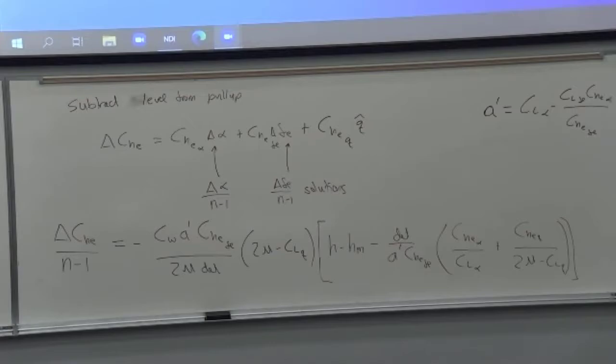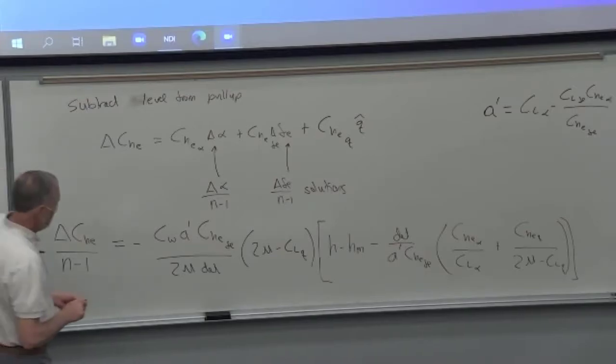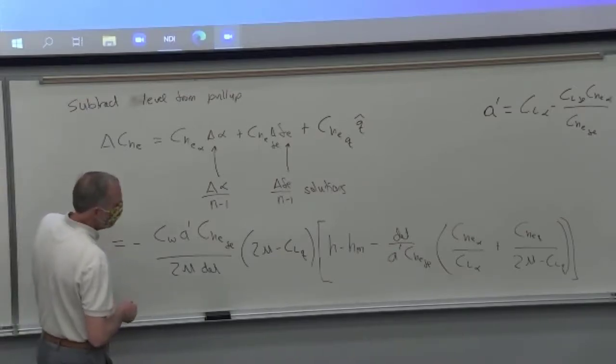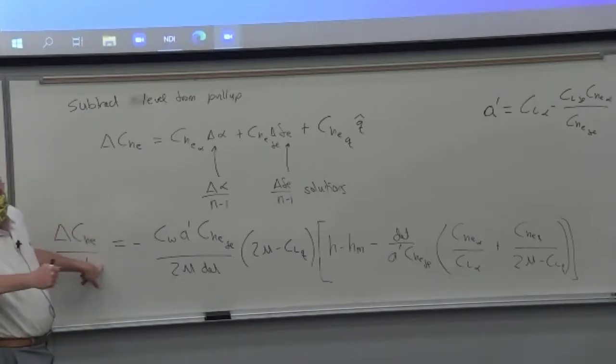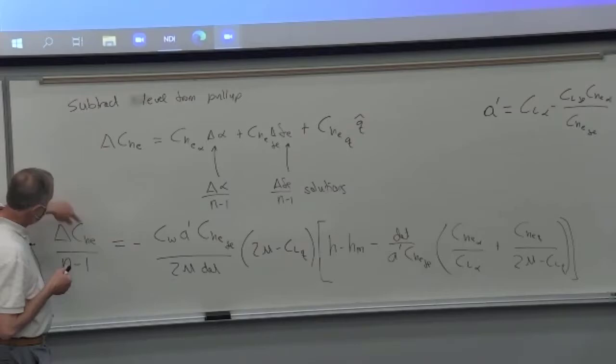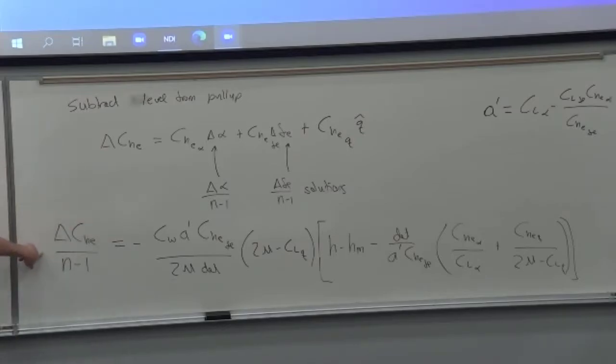Okay, last thing, guess what? We want stick force per G to be positive. We want the pilot to have to pull. So a bad situation would be when this is 0, right? Just like in your car, to do a turn, it takes no force at all to go into the turn. We don't want to do a pull-up where there's 0 stick force per G.